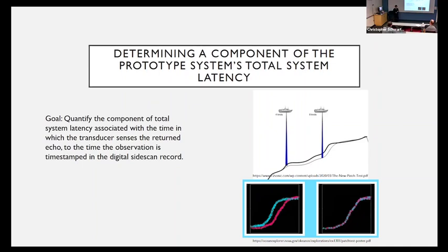We're all familiar with the idea that if we ignore latency in hydrography, we end up with a systematic positioning error, whose magnitude grows with vessel speed. For example, here, if latency is properly accounted for, we get nice co-registered bathymetry regardless of vessel speed. And then if we are improperly accounting for that latency, we wind up with some type of offset like that.